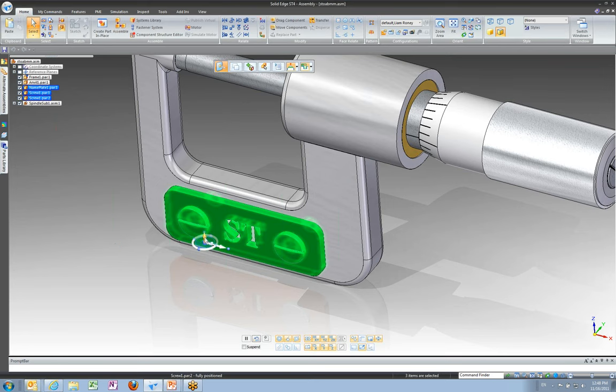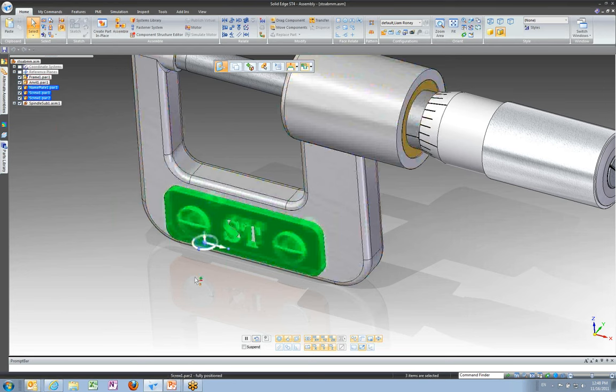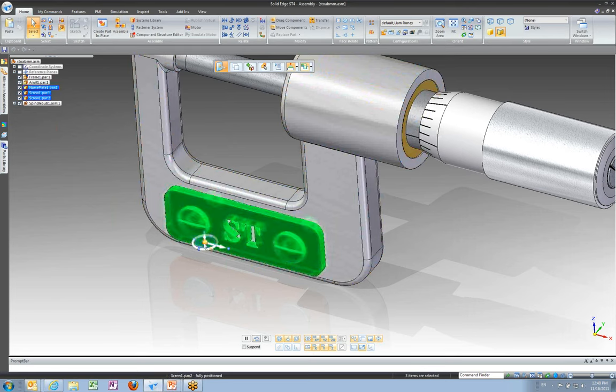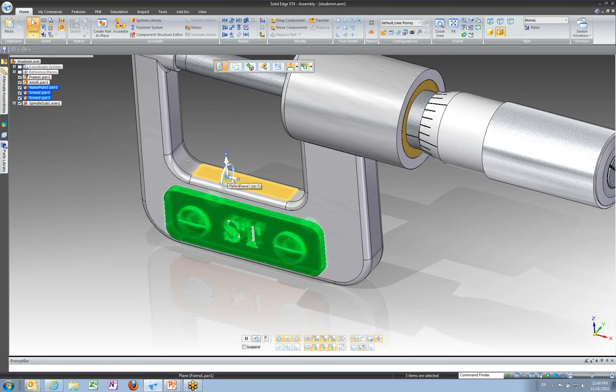The next thing I need to do is set the direction of my move. You see that on my steering wheel, I've already got my minor axis pointed in the upwards direction, which is where I want to move. So that works. But because I want to line that top edge up with the edge of those radii, I want to move my steering wheel to that top edge because that's my reference point. To move your steering wheel, find that center node that I've clicked on here and click it once. That's going to put it on the end of your cursor. Notice as I bring my steering wheel over various faces, it will snap itself to be in alignment with those faces. If you put it over a cylindrical edge, it'll bring itself to the corner of the cylinder.